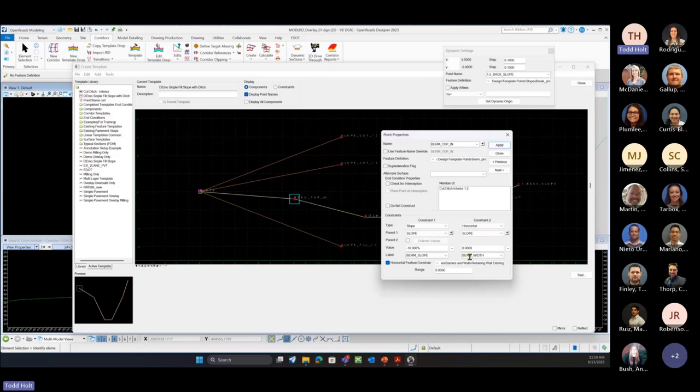For berm width, it's always going to draw it out 8 feet, but then we can add in, let's say, 20 feet. We're going to build an envelope or a range for that to look at and search for a certain feature definition. So maybe we have our roadway design, the plan profile, 2D lines, and we have a slope or a slope break that we're going to use.